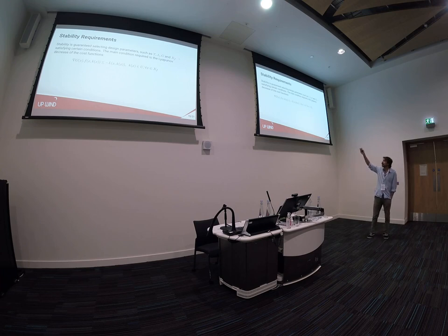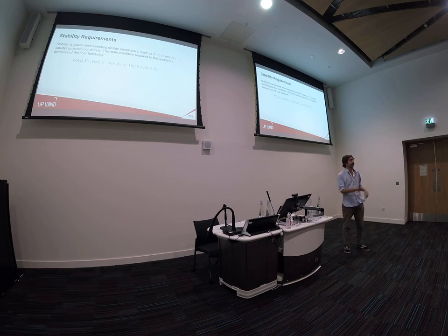So this basically means that, let's say, the rate of change of the terminal cost is less than or equal to that rate over there that is linked to the stage cost. Okay, and this is usually used to prove stability of these quasi-infinite MPC controllers.